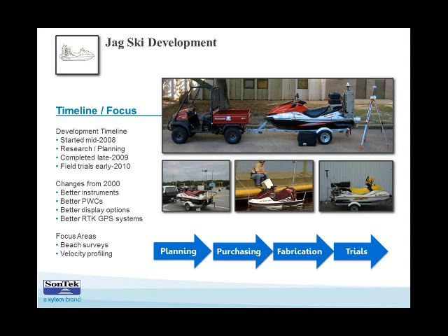But when we do the water quality mapping, we're essentially looking at temperature, salinity, pH, turbidity, dissolved oxygen, colored dissolved organic matter, CDOM, and then fuels and oils. And not surprising, anytime we pass by a boat ramp or a marina, we get spikes in the refined fuels, as you might expect.